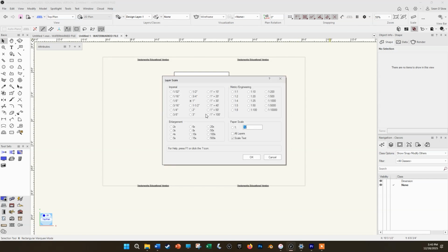But if you're drawing a light plot for a huge arena stage, you might need a 36 by 24 inch architecture D size plate in 1/4 inch or even 1/8 inch to the foot scale. For our door flat, 11 by 17 paper in 1 inch to the foot will work fine, although scenic elevations are typically drawn in 1/2 inch.